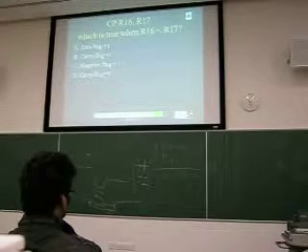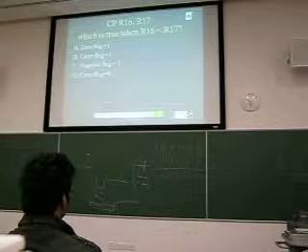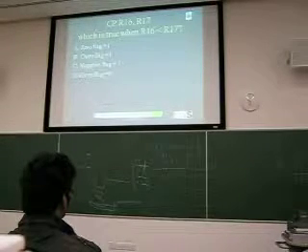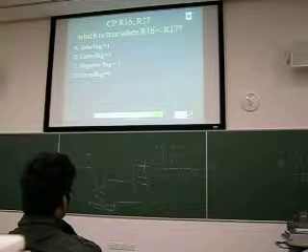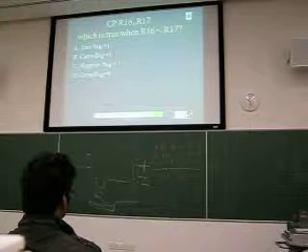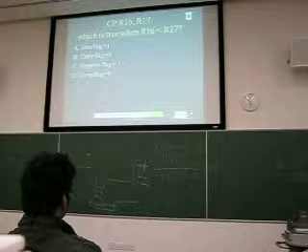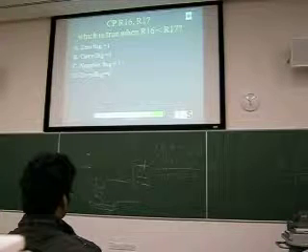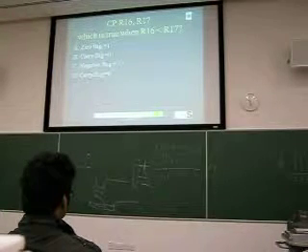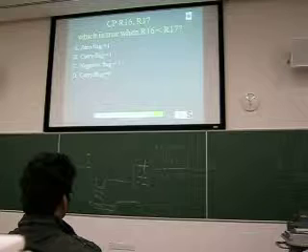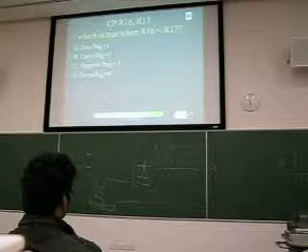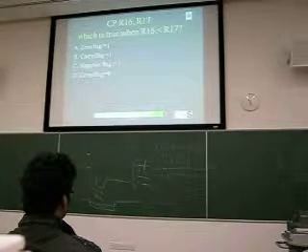Daniel? Which flag? I went with the negative. Yeah. So I figured what happened in the first one is CP takes the second register from the first register, so returns a 0 flag, because it will be 0 if they're the same. So this one, R17 is greater than R16, when it takes R17 away from R16, it will return negative. Okay.